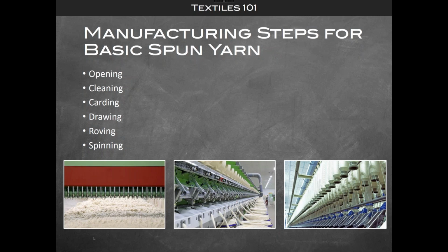After the fibers are cleaned, the next step is carding. Carding is a process that's like taking two brushes, moving in opposite directions of each other. Carding is what helps the fibers align into one single direction. After carding takes place, the next step is drawing.